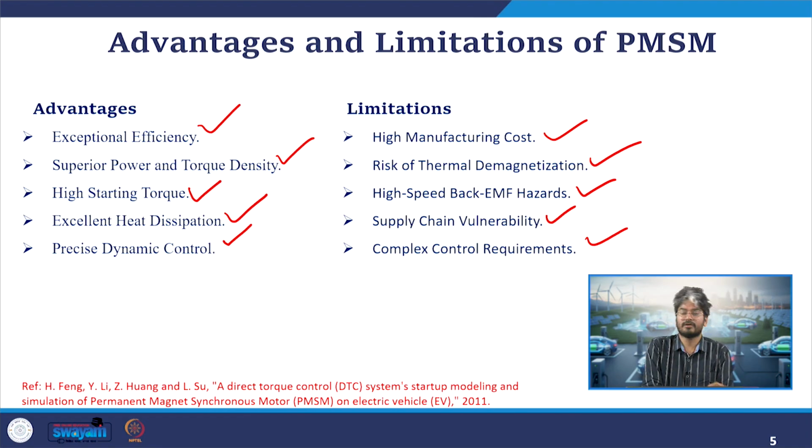So there are two options: either we go for ramping up the frequency, so that frequency will be slowly increased and the rotor will slowly catch up the speed, or we can have some position sensing and directly start the vehicle. Based on the cost and other design factors we will choose any one of them. The control complexity will be a bit higher compared to the induction machine, which is a self-starting machine. In that induction machine we do not require any position sensing, because it is self starting. The moment we connect an AC supply, it will start rotating.